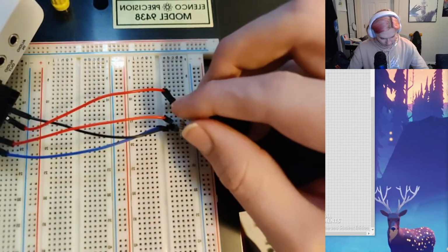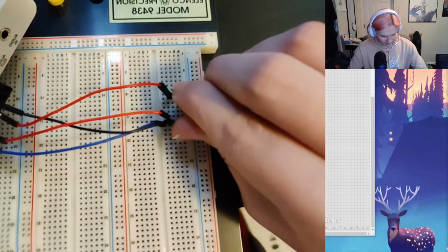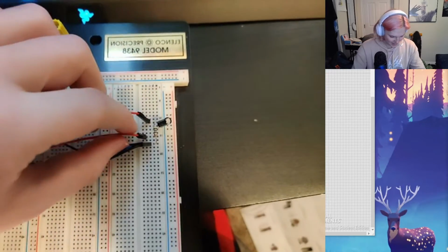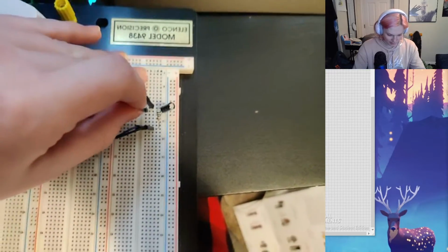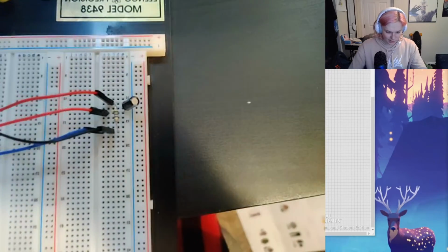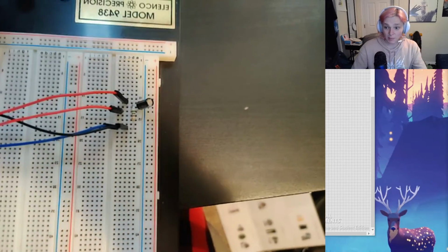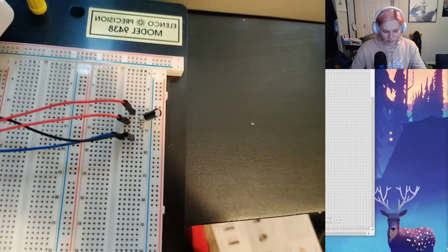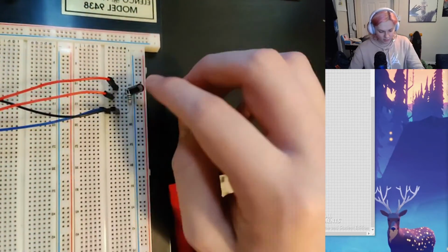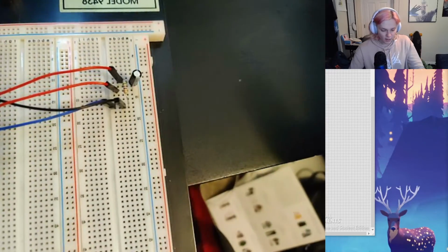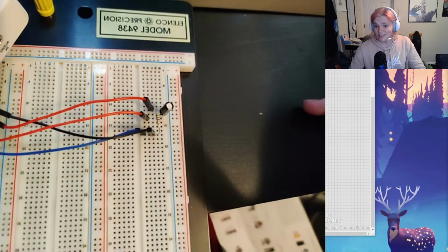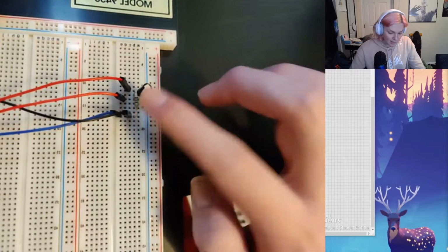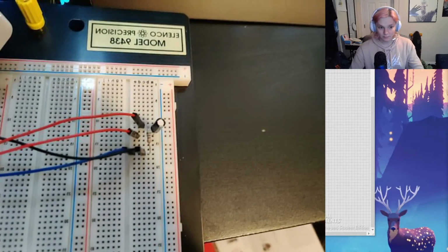Sorry, this is tough to do one-handed. I'm holding the camera with my other hand. All right, and now we want to make sure that we are just reading the signal across the resistor. So now we have made a high pass filter, and you may want to refer back to the stuff that you did earlier in this lab. I believe it's experiment 3. That shows how we can turn this very quickly and easily into a high pass filter like this.